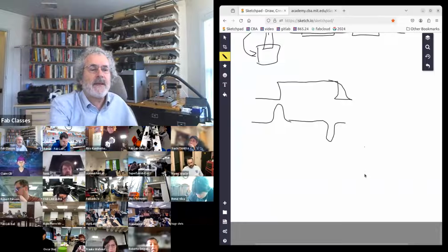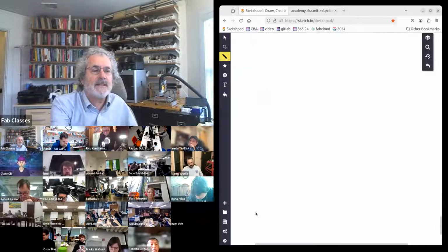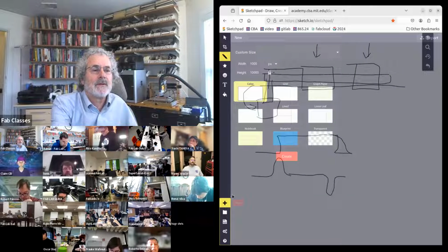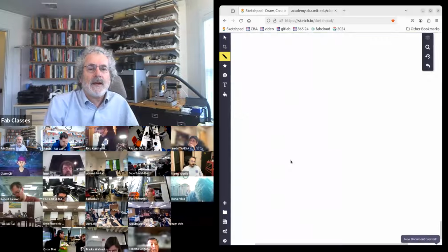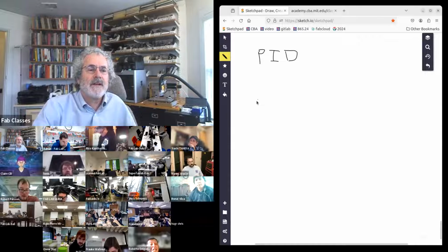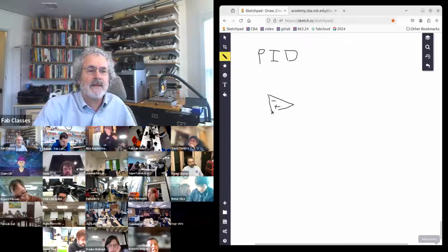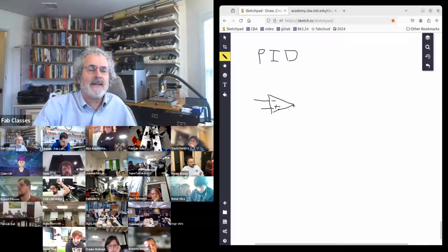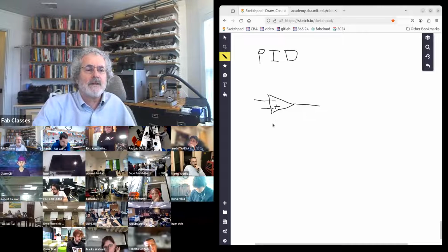PID has been around for ages. PID stands for proportional integral derivative. So we have two signals. We have where we are and where we want to be. And you can take those two signals and you can get an error signal, and you can use that as part of the controller.